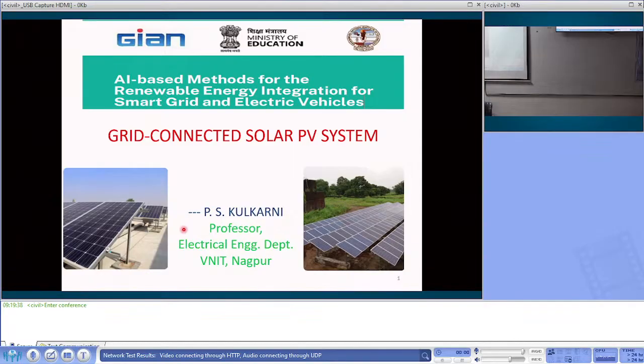The analysis of such a plant is different from the analysis of a thermal power plant. Thermal power plant or any plant will have fixed cost and variable cost. In a thermal power plant, fuel cost is the major variable cost, apart from operating and maintaining expenses and labor cost, which come under variable cost. But here there is no fuel cost involved.